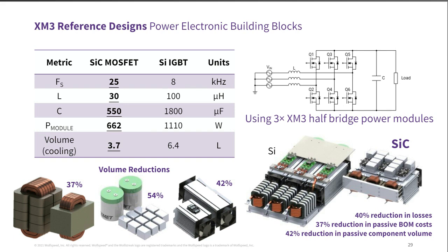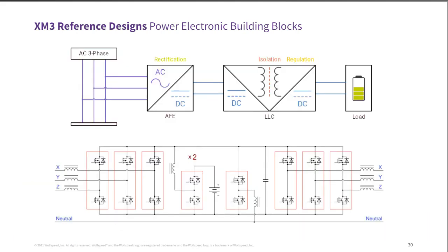So these kits, the 300 kilowatt and 600 kilowatt, can be implemented as an inverter or as an active front end. So again, back to the same kind of charger topology that was previously touched on, the two-stage, utilizing the inverter kit as an active front end to then have something like an LLC stage on the output to provide a really high power DC fast charger.